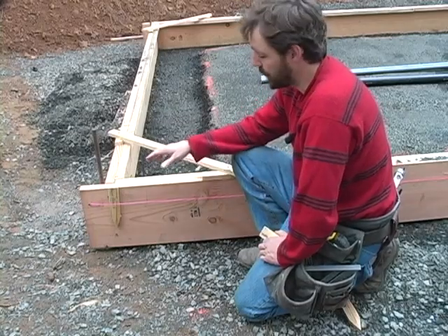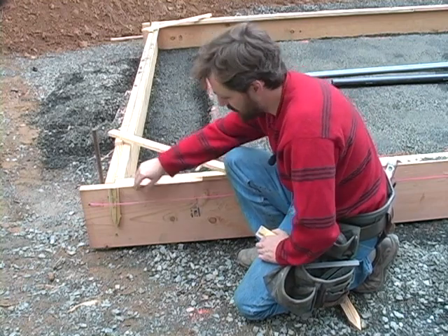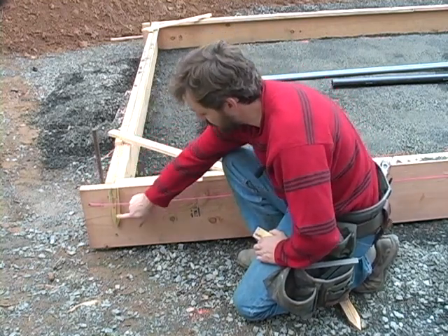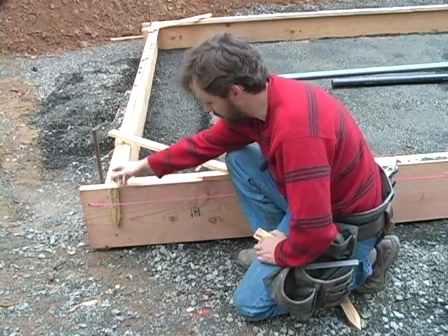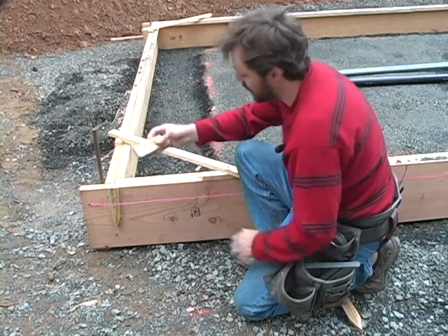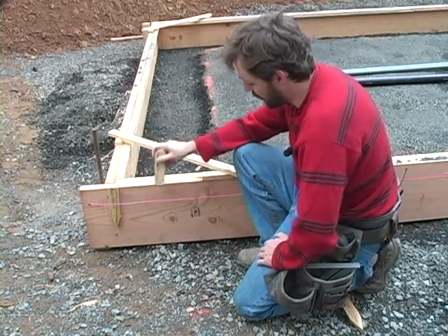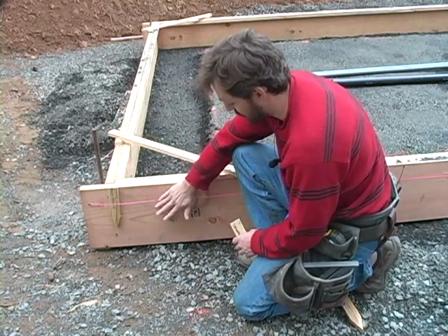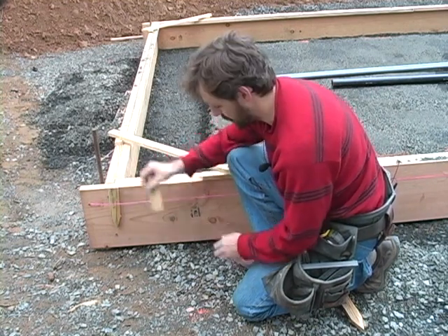In order to ensure that our form boards are straight, I'm pulling a string line from one end to the other. The way I set this up is a screw back on the form board, pull your string across a wood block. If you have plywood, that works the best. Wood has a tendency to split out, but this is what we had on site. And then I have a second block at the other end and a third block in my hand. This third block I can use to slide and check the space between the form board and the string line, because I know it should be equidistant to this thickness right here because it's the same piece of wood.